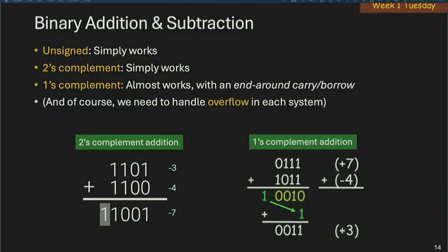In unsigned, overflow equals carryout. In 2's complement, that's when you have 2 negative numbers, but you get a 0 over here, meaning that the result is a positive number. Right? Something that is obviously wrong in terms of the sign of the inputs and outputs. That is the overflow condition for 2's complement and 1's complement. But other than that, 2's complement works just so well. You can just ignore the carry, and if there's no overflow, the remaining 4 bits will be correct.